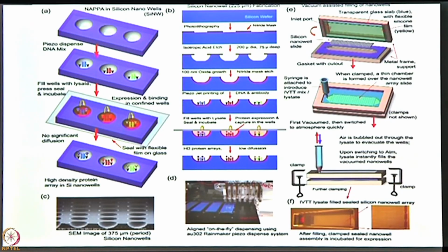So while I describe it like it was easy, this is actually quite an involved process to get to work. It took a lot of different mapping methods on the photolithography side to create wells that had this sort of bowl shape at the bottom, because typically photolithography wants to make a straight wall and a flat bottom, and it turns out that the signal intensity was not as good in that format.